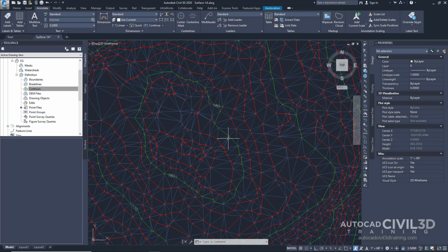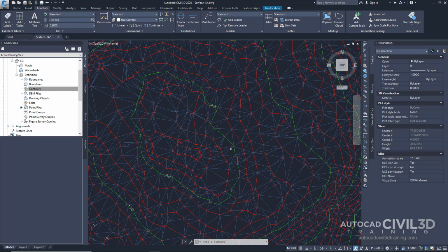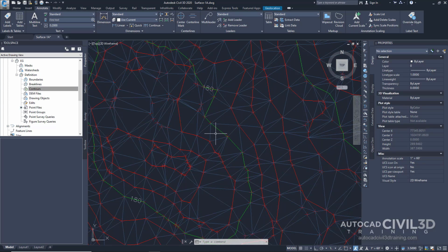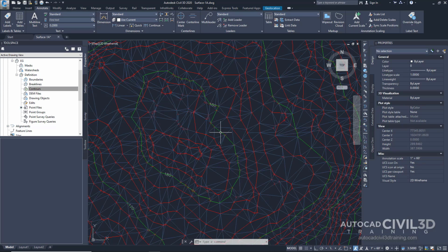In this example, again, we created our contours based upon point data that we inputted into the drawing, but you don't necessarily have to go that route. Instead, you can always bring in 2D or 3D polylines, and just so long as those lines have X, Y, and Z coordinate data, you can add them into your surface by clicking on Contours and clicking Add.